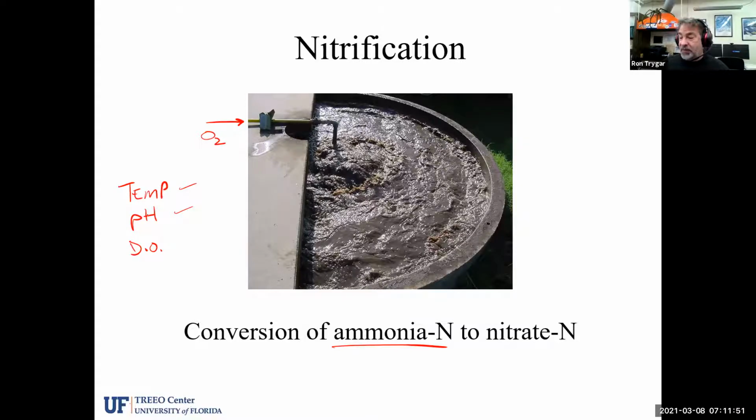So those two things have to be done in the field because those will change rapidly and must be done within 15 minutes of sample collection. Even dissolved oxygen is something that is better measured in situ, in the actual liquid itself. So the ammonium that we pointed out here is a common term. We say it's the conversion of ammonia, but I think it's important that we recognize that at a certain pH value, say 7.0 to 8.0, it's usually in the form of ammonium, which is NH4+. Okay, so we'll talk about that as we go through.